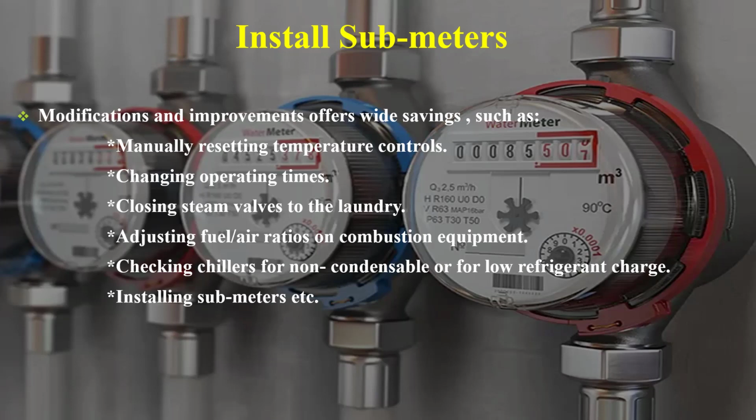Install submeters. Modifications and improvements offer wide savings, such as manually resetting temperature controls, changing operating times, closing steam valves to the laundry, adjusting fuel or air ratios on combustion equipment, checking chillers for non-condensables or for low refrigerant charge, installing submeters, etc.